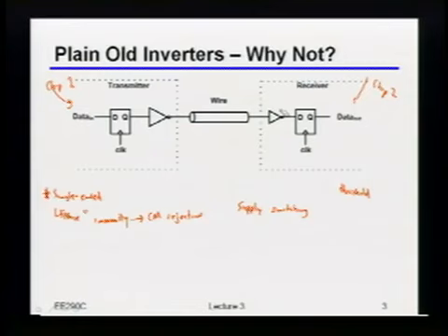So the grounds on the two are not the same. Ah, there we go. So the grounds on the two, even if I had this big, huge PCB, and I actually had a big ground plane connecting things together, sorry, they're 36 inches apart, right? Ain't no way in heck that the ground on this particular chip is the same as the ground on this particular chip. Now, turns out there's even something bigger that's going to exacerbate that particular issue. And so, by the way, just to highlight that, I'm going to draw sort of a big inductor between the grounds over there. Anything else related to the power supplies?